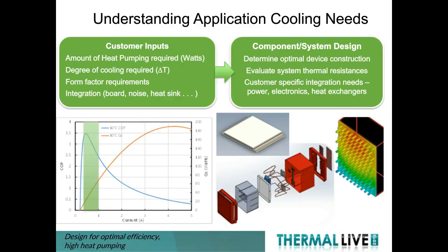And if you were to PWM a bucked voltage rail to reduce capacity for the system, what you end up doing is basically delivering a full voltage signal to the device, and it will act and behave as if it is at that rail voltage, and the PWMing is simply bleeding efficiency out of your system.